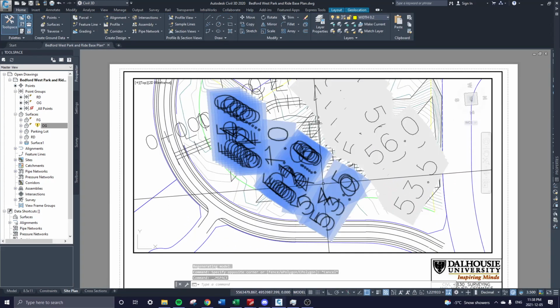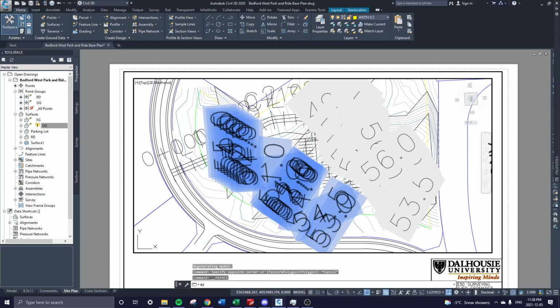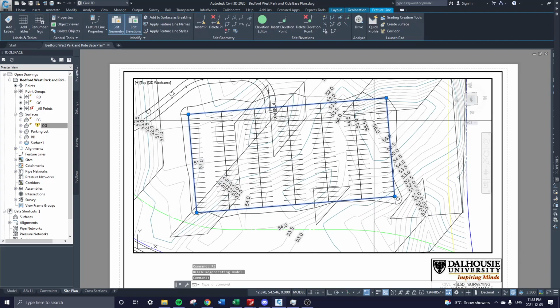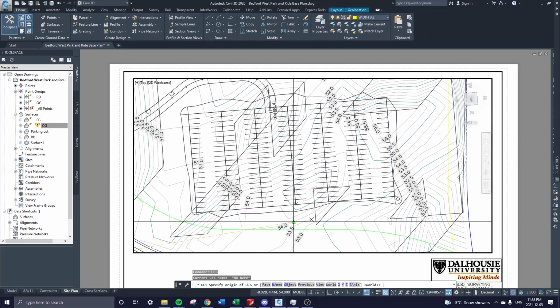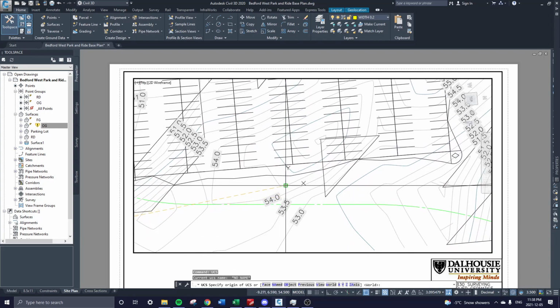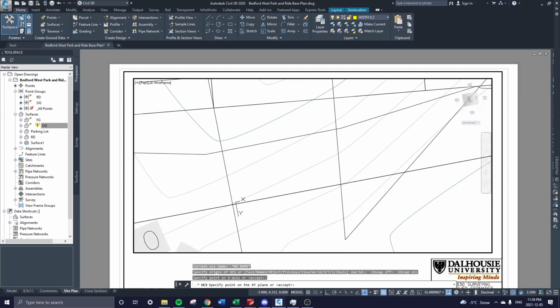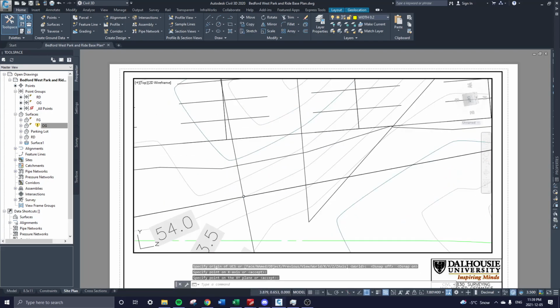And then you can just zoom in again, type RE for regen. It wasn't quite perpendicular. You can select this, but make sure it's not a feature line or a contour. I was telling a student this before the test last week: if you select a contour, you see how that really messed up the X dimension?